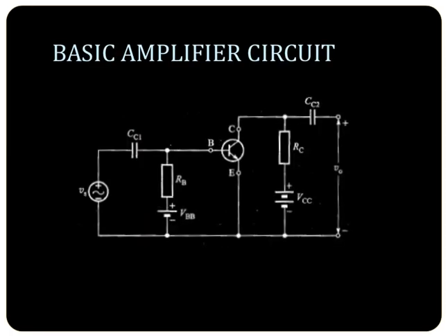Now this is the basic amplifier circuit. You can see what an amplifier is. It is used to amplify a small voltage signal, or you want to amplify the voltage as well as current of this particular signal, or the power has to be amplified. Here this small AC signal is applied to the input of a common emitter connected transistor. This is an NPN transistor, and the biasing is done like this.